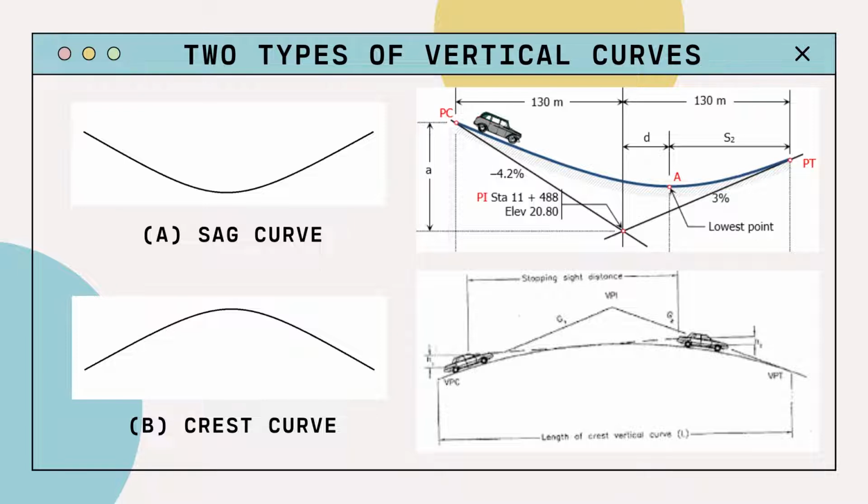There are two types of vertical curves, sag vertical curves and crest vertical curves. Sag vertical curves are curves that connect descending grades, forming a bowl or a sag. Designing them is very similar to the design of crest vertical curves. Once again, the sight distance is the parameter that is normally employed to find the length of the curve, while crest vertical curves are curves that connect inclined sections of roadways, forming a crest, and they are relatively easy to design. The principal control in design of crest vertical curves is to ensure that the minimum stopping sight distance, or SSD, is available throughout the vertical curve. An appropriate length of curve is required that will accommodate the correct sight distance.